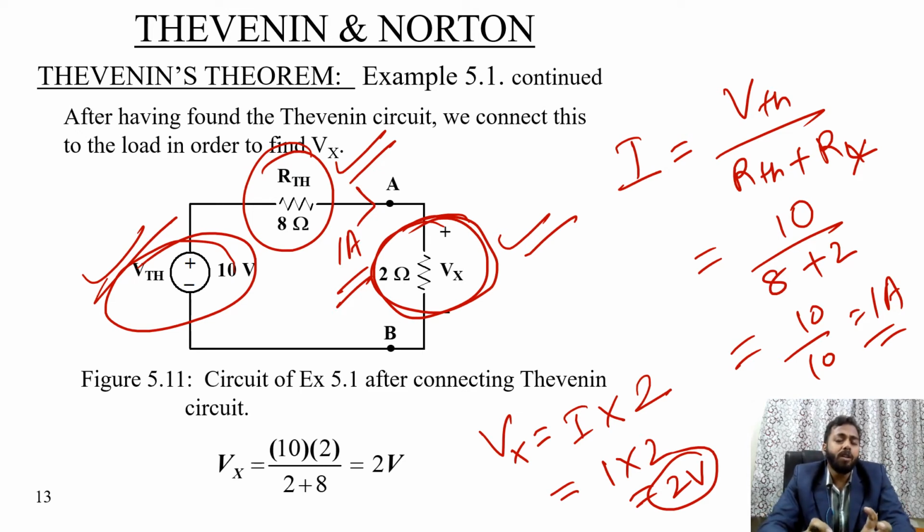This is the maximum power transfer theorem where the load resistance is variable, and when the load resistance is equal to the source resistance, only then the maximum power can be transmitted from the source side to the load side, and we can find out the voltage drop across the load in a better way, and that is equal to what? V square over R, actually the power in the load, that is the maximum power, in that case when the source resistance is equal to load resistance. Okay, we will discuss everything: Norton theorem, Thevenin's theorem, maximum power transfer theorem, superposition theorem, everything in the subsequent lecture.